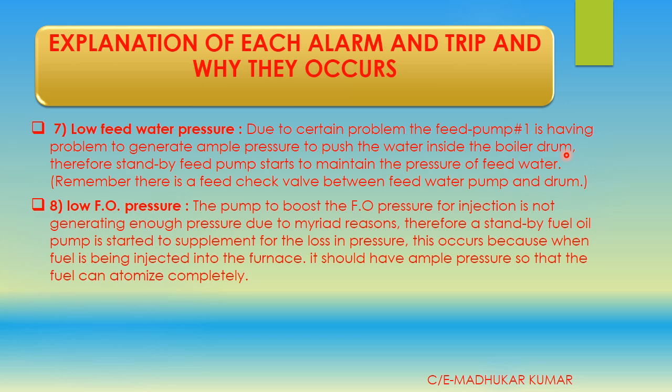Then what will happen is that the standby pump starts and maintains the pressure of the feed water. So you will have the standby pump start alarm also. Remember that there is a feed check valve between the feed water pump and the drum. Of course, there is a feed check valve fitted there.